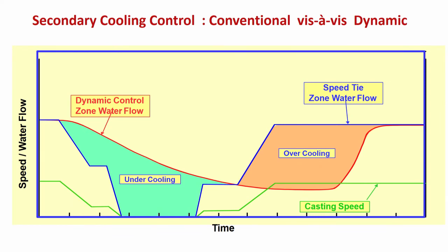So, what do you do in such a situation? If there is a dynamic control, then it changes slightly beforehand. That means, when you get a signal that yes, now we have to change the speed, slightly beforehand you change the amount of water. So, this is what is happening. This amount of water is now following this path, this red one, and then when you get a signal that the speed has to go back again, before that you again increase the amount of water.